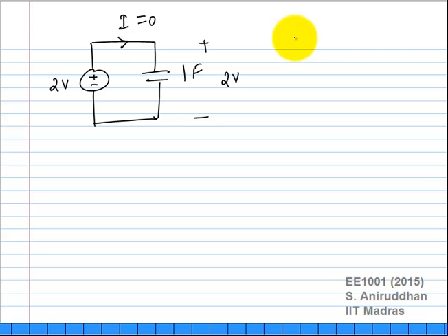Let us assume that the capacitor has no voltage across it and you are connecting it like this. 0. Why? It will be instantaneous, right? The charging will be instantaneous because you don't have any resistances in the circuit. We assume ideal wires. KVL has to be satisfied at every instant, right?